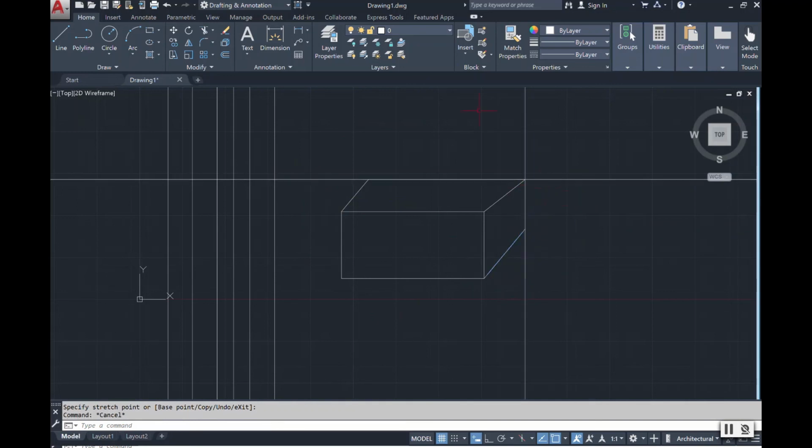And I need to just move my guidelines that I created. So I'm going to select those all together and get them out of there. Now I have a line that's extended. Remember, when you have a line that you need to shorten, you can select it. When you get your blue grippers, you can pull it back to where you want it to end.